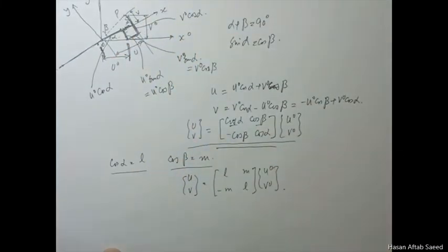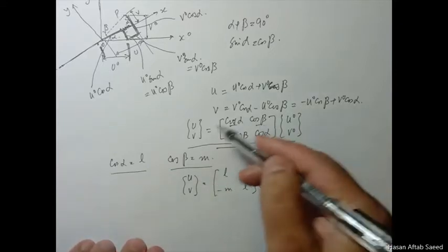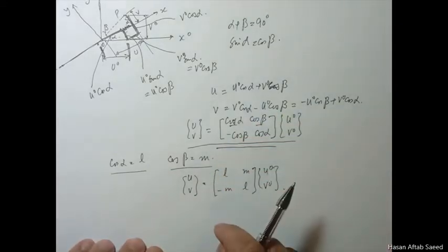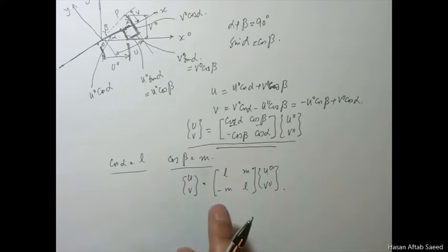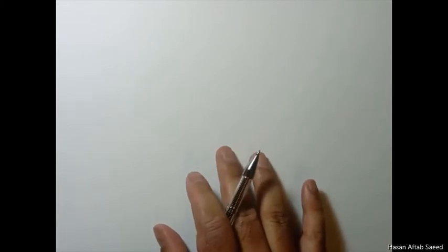But if you consider that each truss member has two such points, two nodes I and J, obviously, and I and J both transformed by the same transformation equations, so we can extend this to a system with two nodes. And obviously we don't need to derive that again because we have already done the derivation. The second point should also transform in the same way.